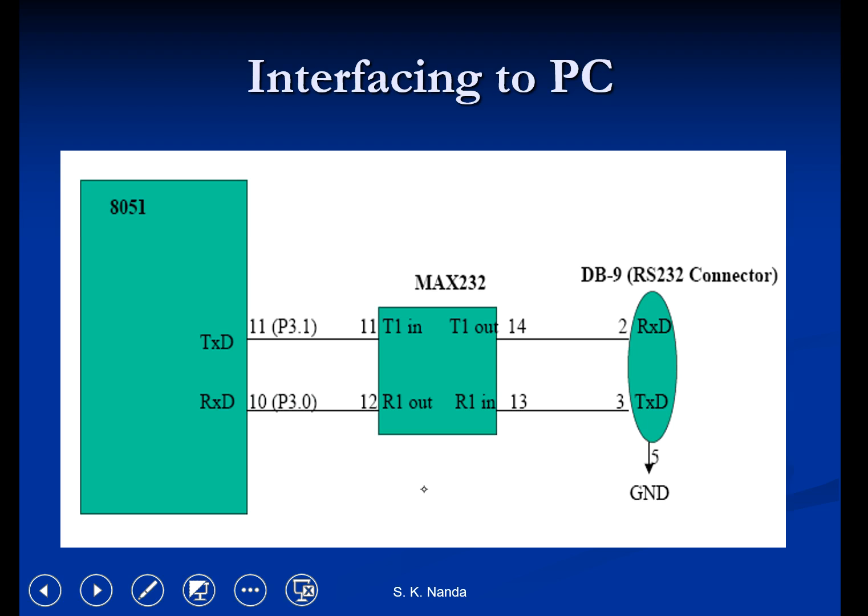IBM introduced the RS-232 version of the serial I/O standard, which is most widely used in PCs and several devices. The range minus 3 volt to plus 3 volt is undefined. The TTL standards came a long time after the RS-232 standard was set.